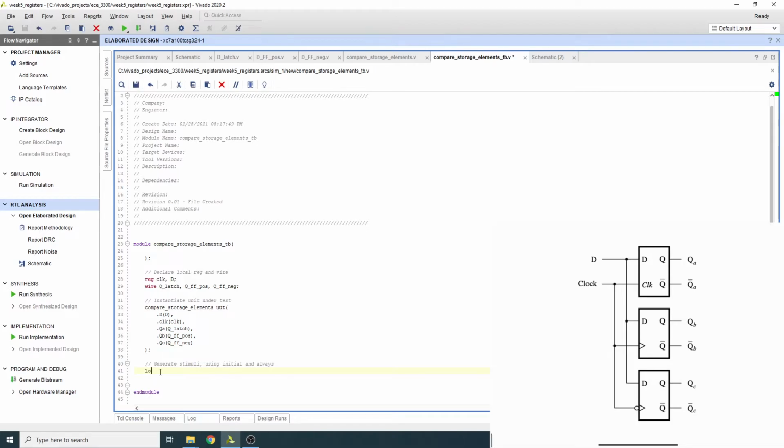So what we're going to do is define something we call a local parameter. A local parameter is like the parameters we've been dealing with, it's just not exposed outside a module. If you're writing a module, usually you write the parameters next to the inputs and outputs, and local parameters inside. You can use parameters, there's no difference, but just so that you know if you've seen it.